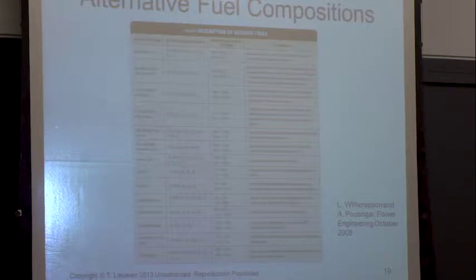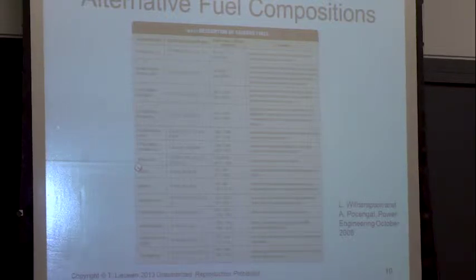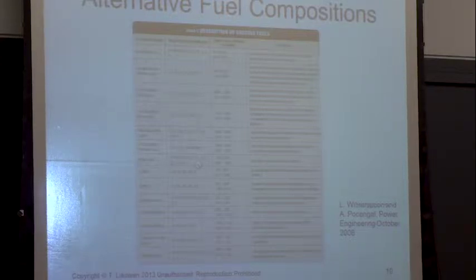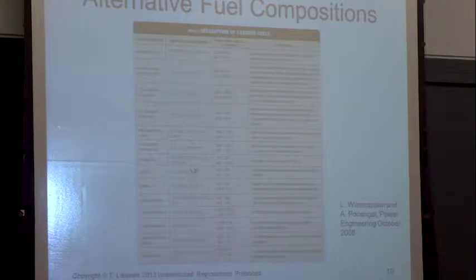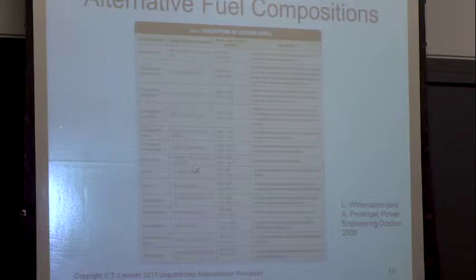Landfill gas, this is an interesting one. When you have anaerobic decomposition of organic matter, you generate a lot of methane, but you also generate carbon dioxide. There are a lot of landfills around. We used to just vent this stuff into the atmosphere, but nowadays most landfills are capturing that natural gas, and in many cases burning it on site with either a reciprocating engine or a gas turbine engine.